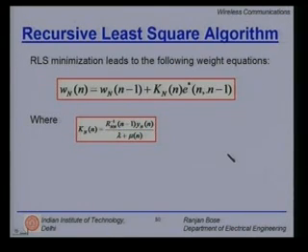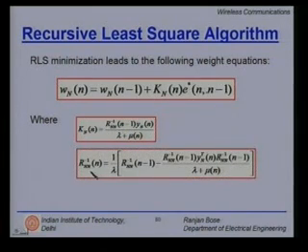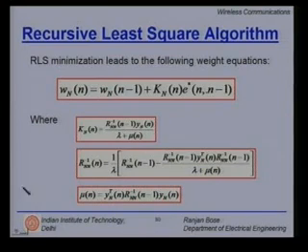So, we are not going through the whole derivation. Again, you can consult Proakis, Digital Communications, to go through the derivations, but this is the final crux of the matter. This is the weight vector definition. Here K_n is given by the following equation, and R_nn inverse can be expressed as follows. This is the input covariance matrix, and mu_n, which is used here, can be found by this method.